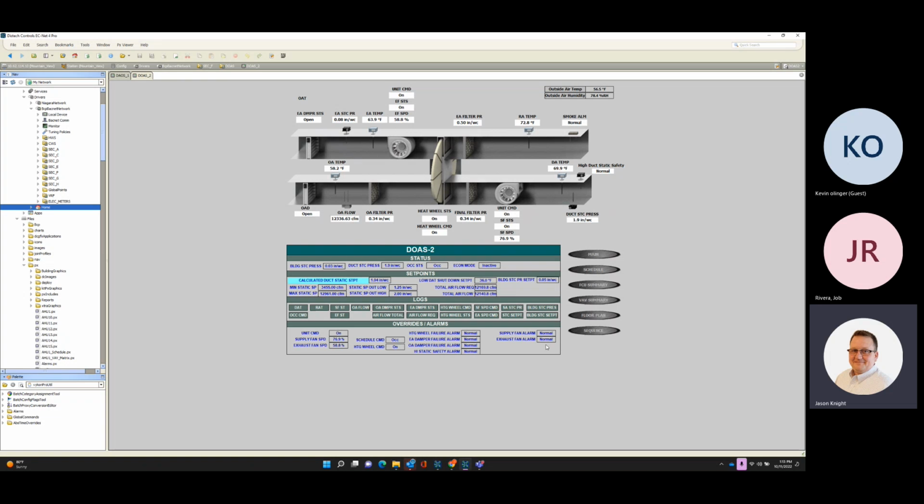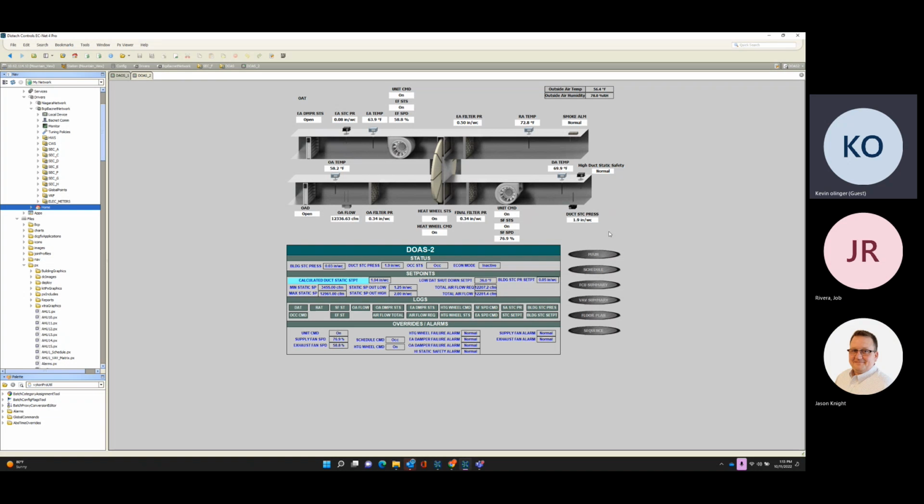And you know what I could do, Kevin? I could put a little note on the graphic, because these DOAS units are individual graphics, that I could say this unit has ECM motors, this unit has VFD motors, or these outside air dampers are 0 to 10 volt. These outside air dampers on these units are 24 volt on or off. The control drawings will show that, won't it?